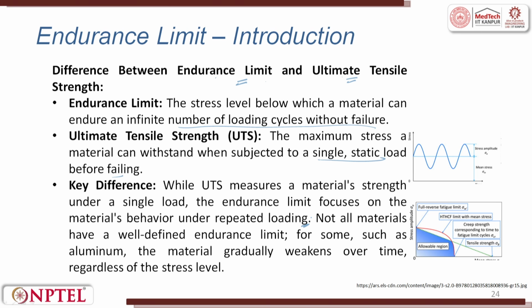Not all materials have a well defined endurance limit. For some, such as aluminum, the material gradually weakens over a period of time, regardless of the stress level. So, you can see here how the plot is made, and here we try to find out what is the allowable region, and we try to plan our cycles with respect to stress here,